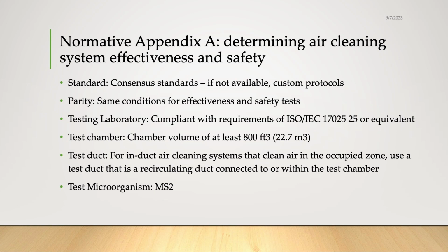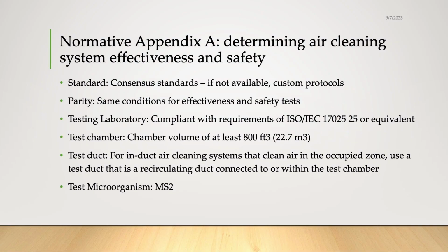Why is that important? A lot of air cleaner tests by manufacturers were done like 100 cubic foot, 10 cubic foot chambers, and they were claiming really high inactivation rates, but the clean air delivery rate that was associated with that was really small. So it has to be a reasonably room-sized kind of chamber. And the microorganism tests all have to be done with MS2 bacteriophage, which is just a way of having a standardized challenge for all of them.